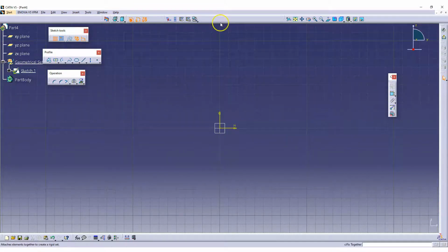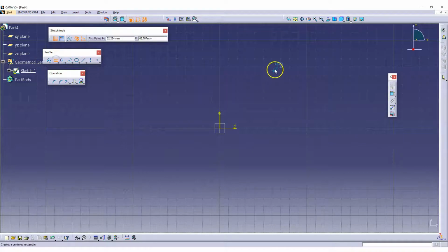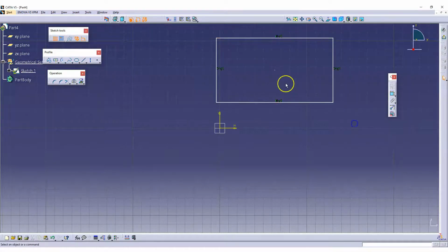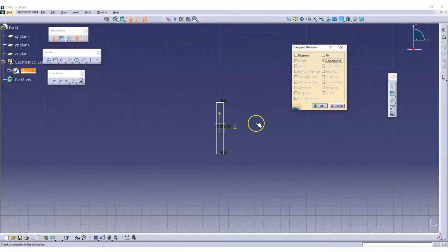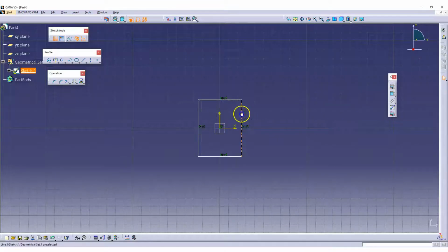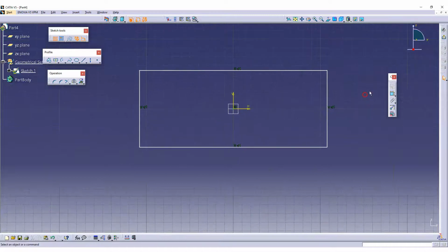So now let's go into it. It should happen. Go to the sketch point. Take this point and this point, and go for constraint. It is happening, right? This is what you're asking, correct? Yeah. So I was switching on, switching off, right? That's the reason it was not accepting it. Yes, it will take that. Now you go and give the dimension.